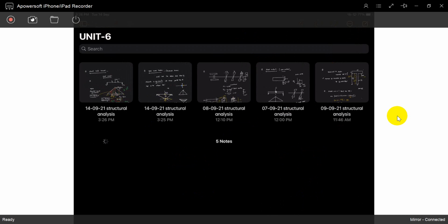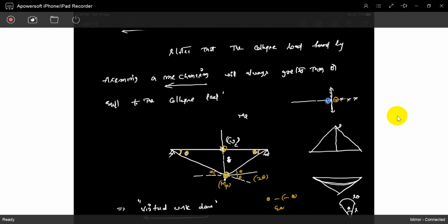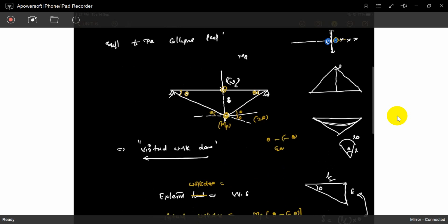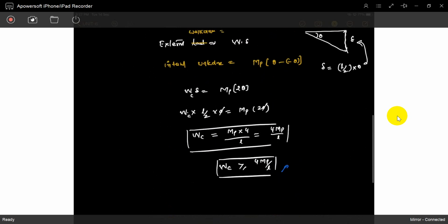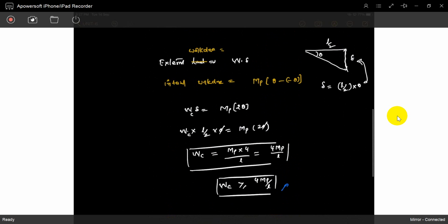So now it's kinematic. It's moving. It's unstable. Understood? What is instability? In the structure, some part or the total body is moving without any force, or if you apply a very small force, it's moving. It is an unstable structure. But we don't take it as unstable. Exactly what we want is that situation at the triggering point. That's why it is just the later situation. That's why it is the upper bound theorem.